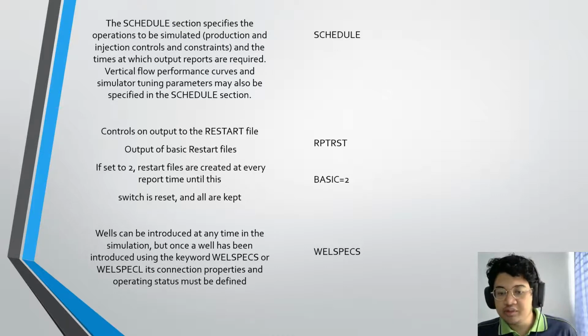To move on with the simulation of the schedule, WELSPECS is written. Wells can be introduced at any time in the simulation, but once a well has been introduced using the keyword WELSPECS or WELSPECL, its connection properties and operating status must be defined.